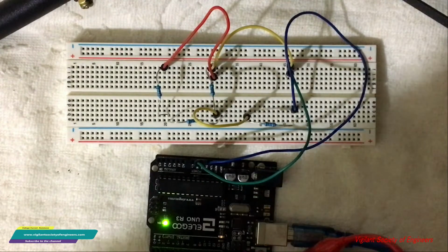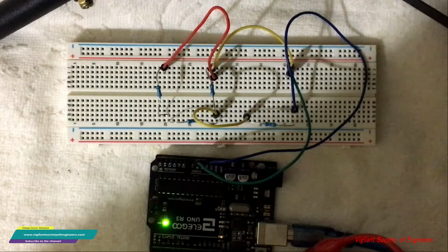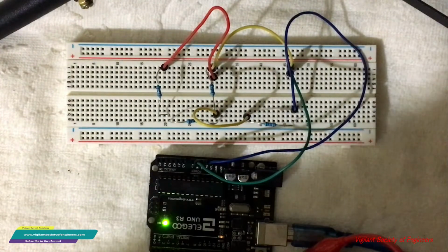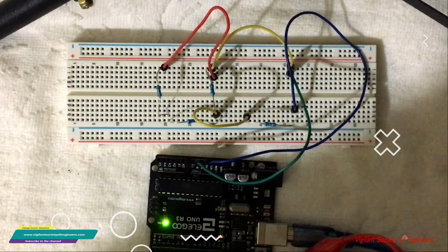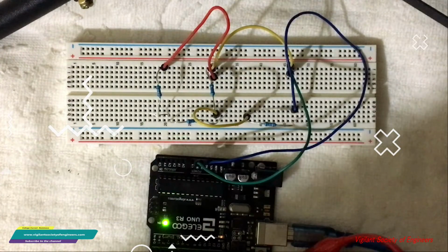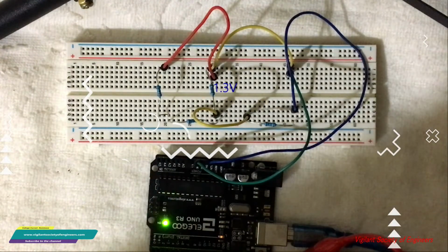All right, so let's look deep into this, as we want to understand how the current and the voltage all split up as it moves throughout the circuit. All right, so we are supplied by a 5-volt power supply from this board here. Across the input of the circuit we have 5 volts. And then that voltage is going to split between the first resistor in series. We're using 220 ohms resistors and a 100 resistor within the series parallel circuit.